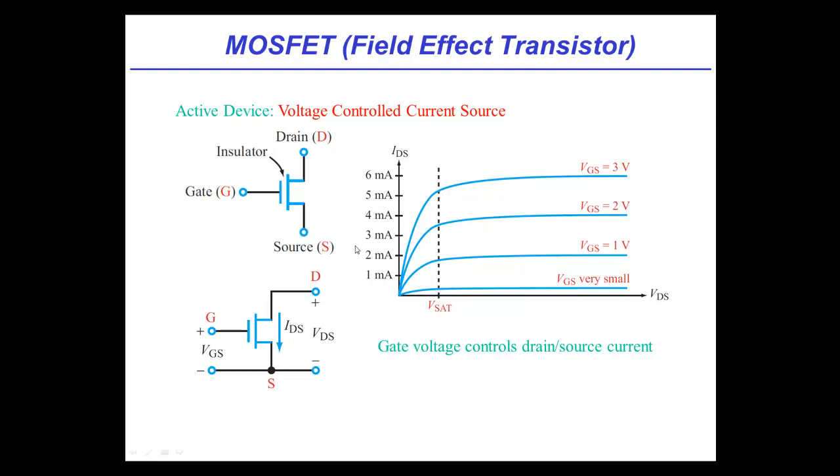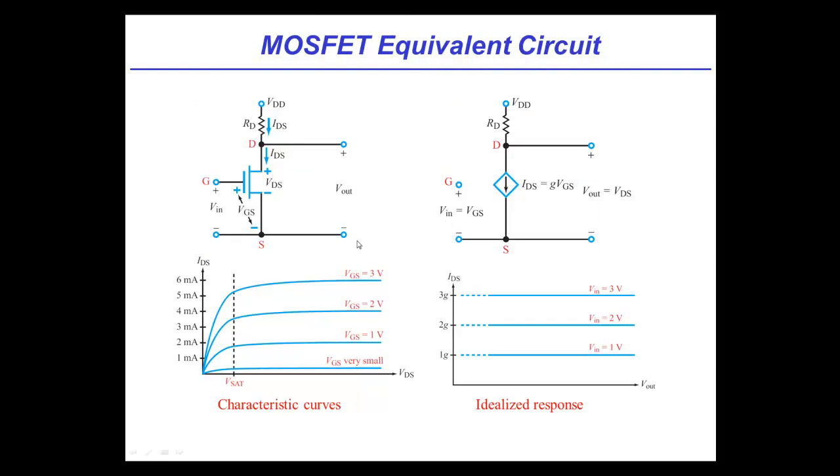So we're going to do very simple examples here just to give you a feel for it and nothing more. Building on what Vivek just taught us, if I take this transistor and connect it to a drain resistor, which is simply a resistor connected at one end to the drain and at the other end to some source voltage, VDD. This could be 2 volts or 5 volts depending on how we set this up. And I'm going to take the source and connect it to the negative terminal. Often you'll see a ground here. Some people say, oh, this is grounded on the bottom.